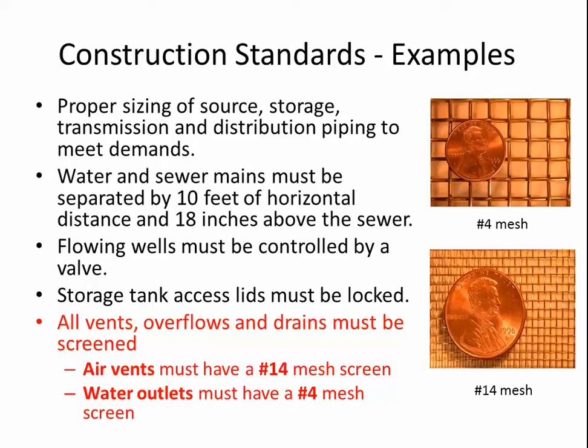Storage access lids have to be locked, and then we're going to talk a bit more in detail about those lids in a minute here. And one thing I want you to remember from this slide, especially for the exam, is that air vents have to have a number 14 mesh screen, and then any water outlet, that's like a drain or an overflow, has to at least have a number 4 mesh screen on it. So remember, the number 4 is for the drains and overflows. The number 14 is for air vents. Promise me you won't forget that.